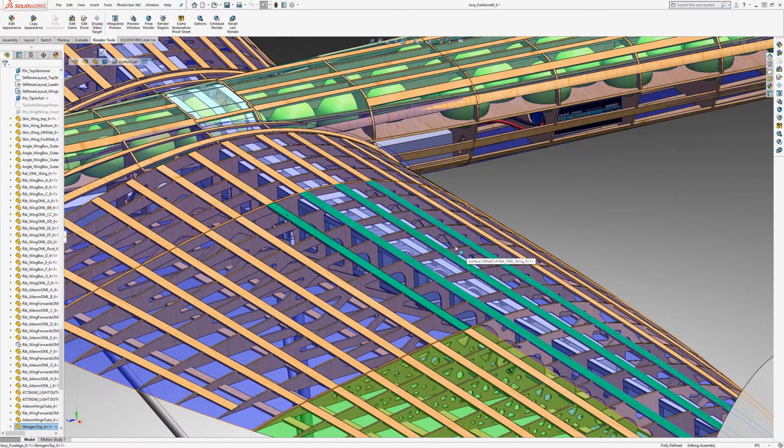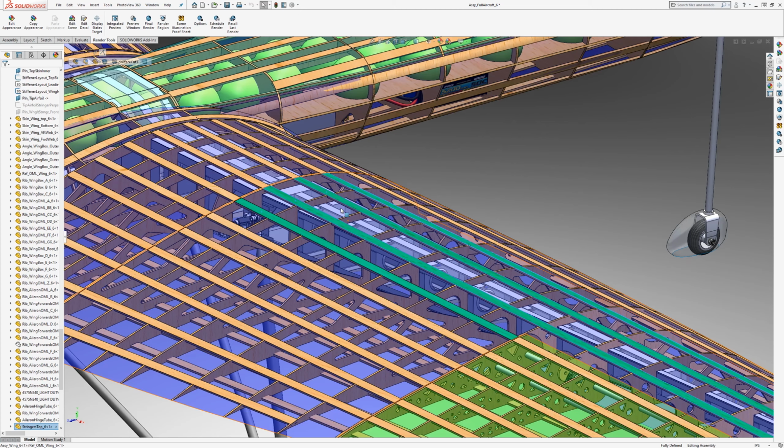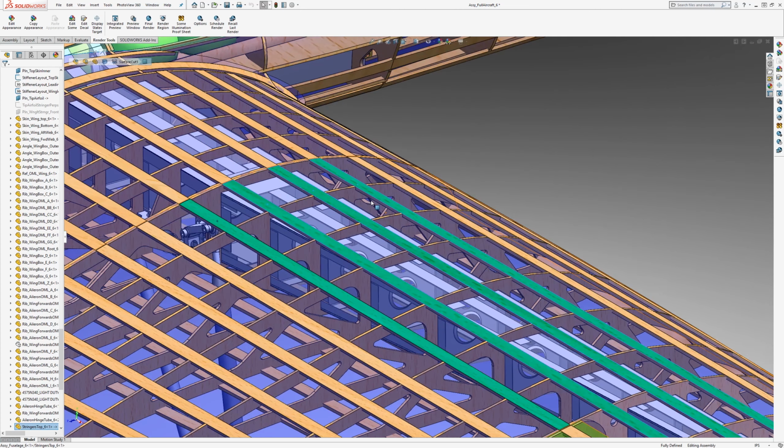There's a good reason why they aren't doing that, at least hardly at all, and their role is almost entirely just to bridge the local loads, the local air pressure, and move it from the skin around them into the stringer, into the ribs, and move that down to the closest internal metal structure and not contribute to the overall second moment of area, like what resists the bending of this wing.